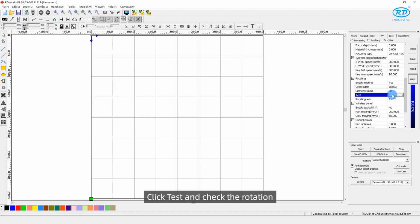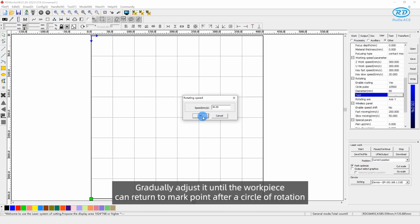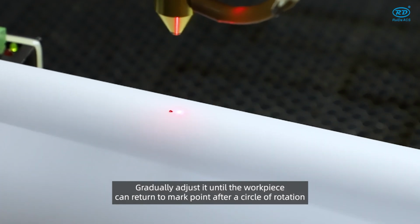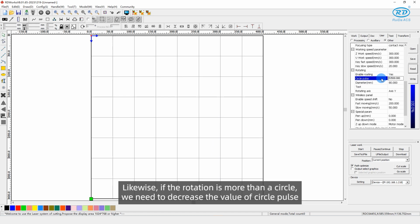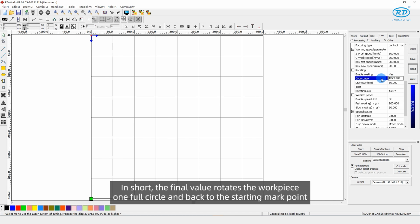Click Test and check the rotation. Gradually adjust it until the workpiece can return to the mark point after a circle of rotation. Here displays the situation when the rotation is less than a circle. Likewise, if the rotation is more than a circle, we need to decrease the value of circle pulse. In short, the final value rotates the workpiece one full circle and back to the starting mark point.